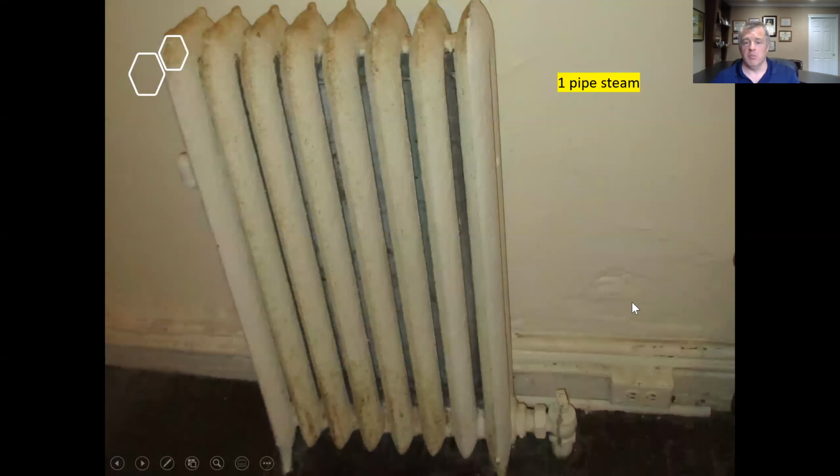One pipe steam, most common in these buildings. If you look at the bottom right, next to that outlet, the steam comes up because steam wants to rise because it's lighter than air. It goes into this radiator. It gives you the nice heat. It cools. It turns to water. It drops because it's heavier than air, and it goes right down the same pipe and passes the steam on its way. If you're thinking, wait a minute, it doesn't seem like a great idea to have cold water pass steam because it's going to take away some of the heat, bingo.